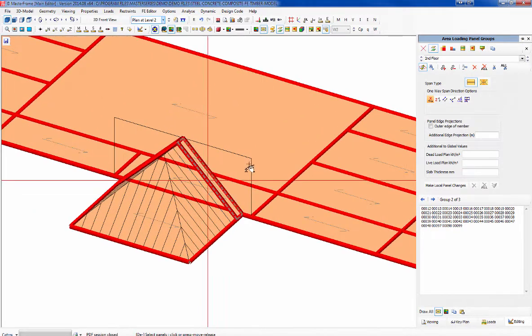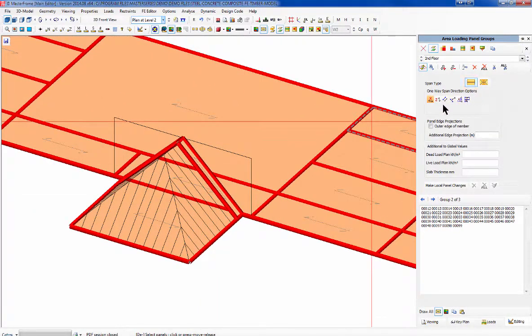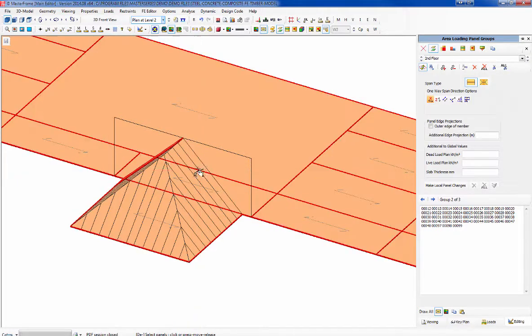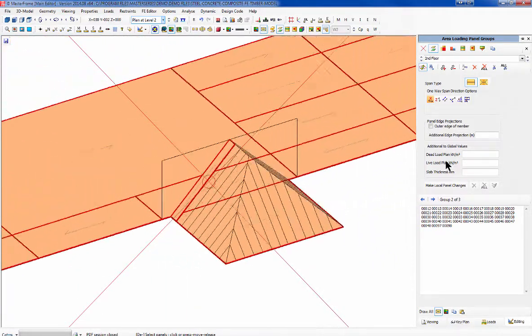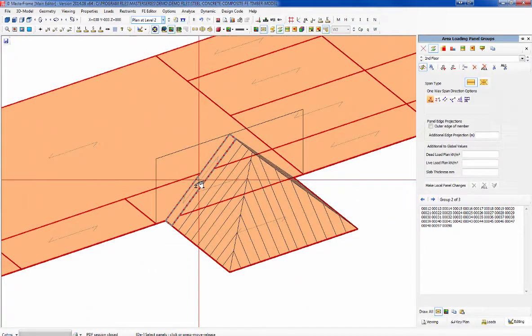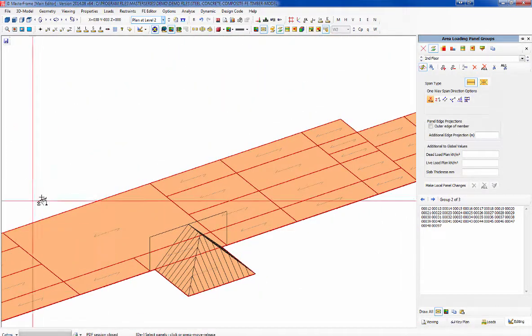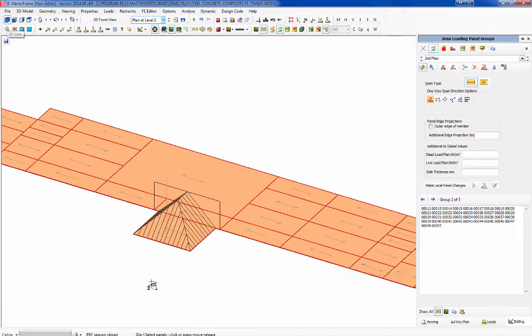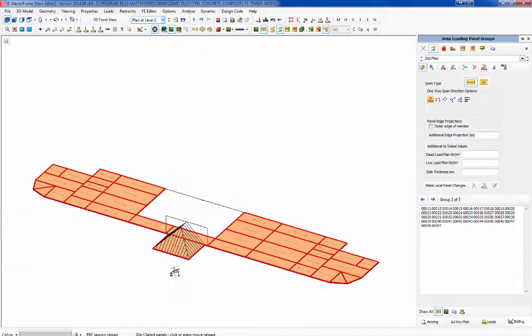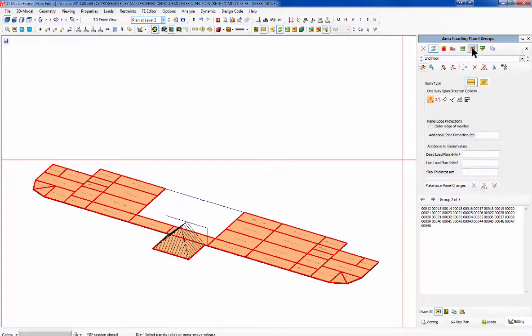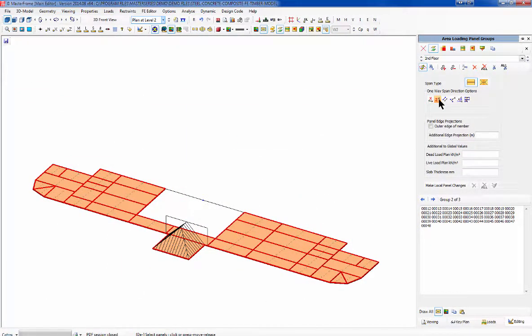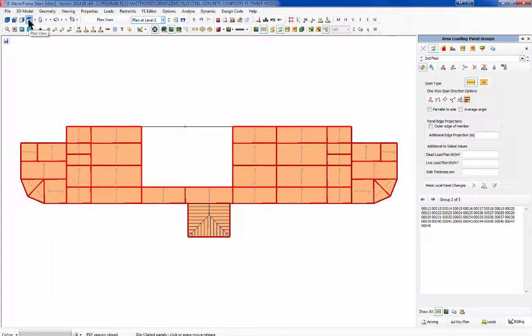So we just take out that one and that one, so it's not on the sloping rafters. So here we go, and we don't need it in here. This is a big opening area, and I don't like the way it's spanning, so I'm going to span it horizontally. Now I can span it shortest so that in each area we get our different areas of span.